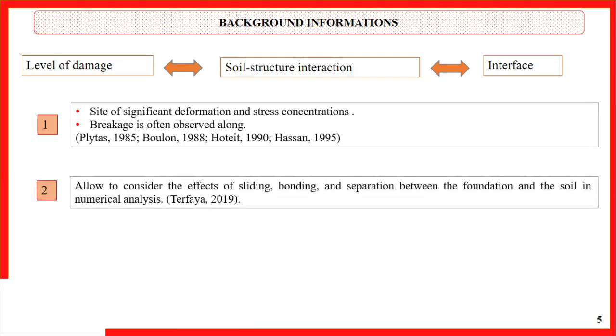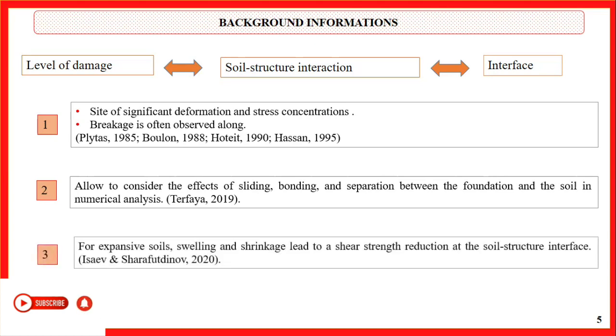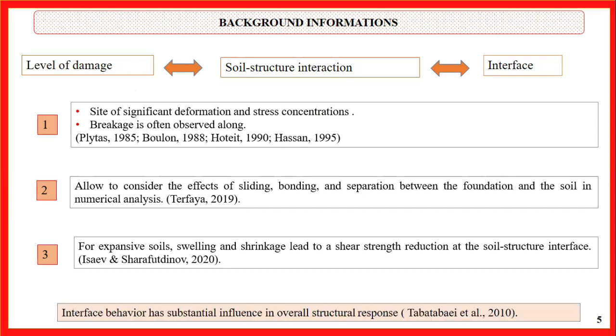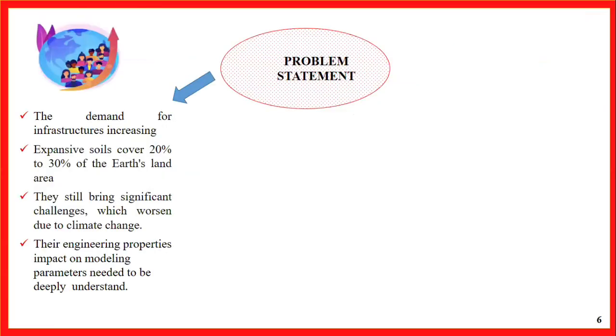In numerical analysis, it is possible to consider the effect of sliding, bonding, and separation between foundation and soil. For expansive soils, swelling and shrinkage lead to a shear strength reduction at the soil structure interface. The interface behavior has substantial influence on the overall structural response.